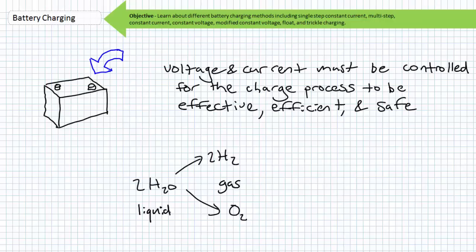Conversely, if charge voltage and current are too low, the recharge process takes too long, if at all. This is to suggest that the charge process is a balancing act, in that voltage and current must be continually monitored and maintained between high and low limits. Further complicating this balancing act is that the high and low limits change as the battery's state of charge varies.